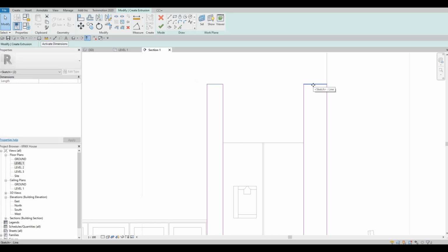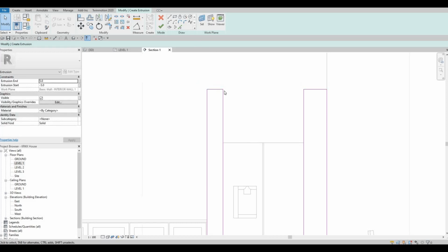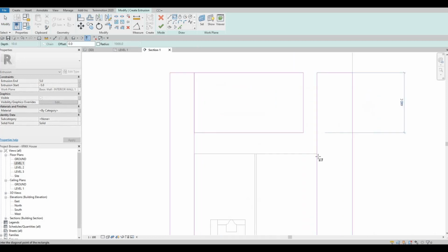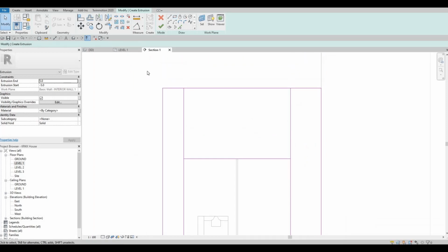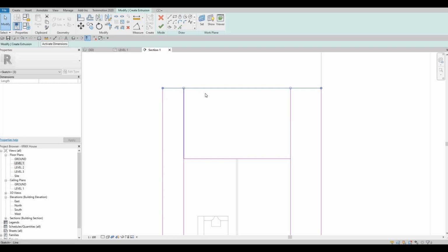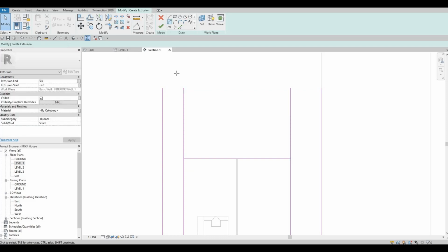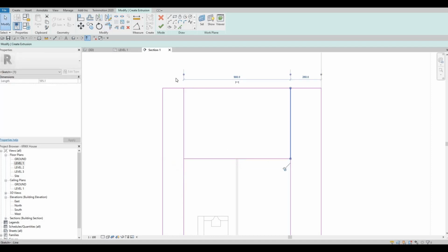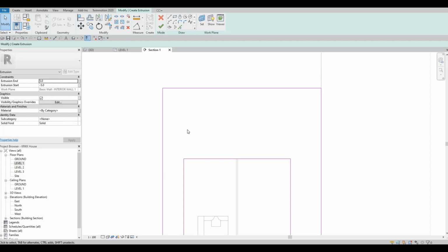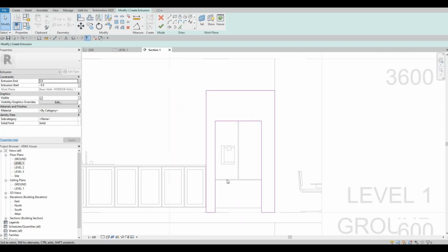So we could just move it down a bit, and then now we could use a rectangle again to quickly add those lines. I know there are overlapping lines right here. We could just select all of that, and then here we could just add one, and then here use trim and extend, TR, and then like that we could just delete the ones that are remaining. So now it will look like this.